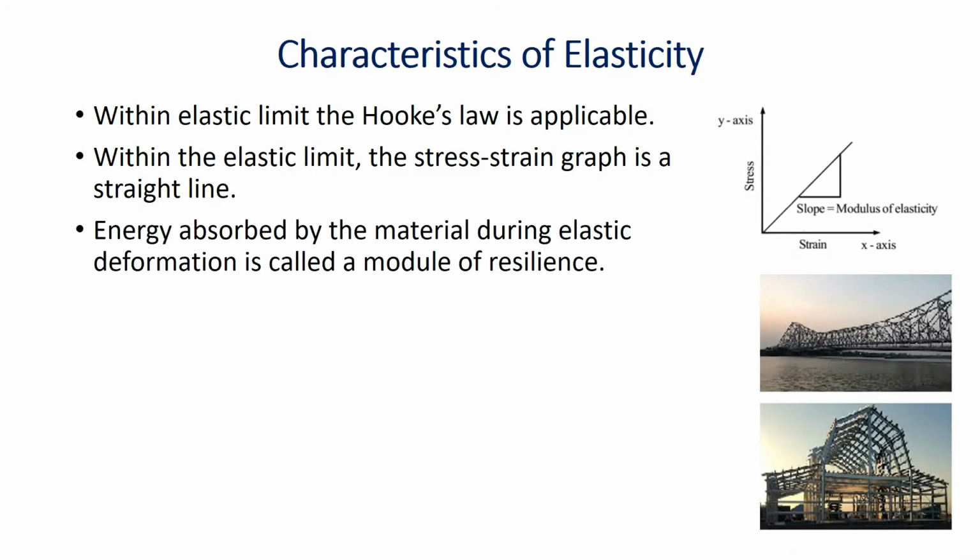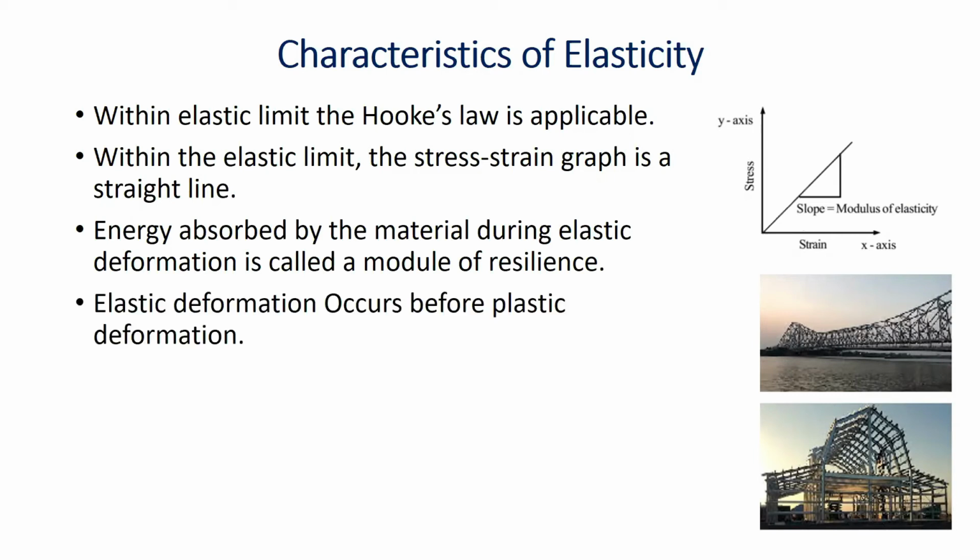During deformation, work is done against the internal restoring force. Hence, potential energy is stored in the body. Energy absorbed by the material during elastic deformation is called the modulus of resilience. Elastic deformation occurs before plastic deformation. Thus, without elastic deformation, plastic deformation is not possible.